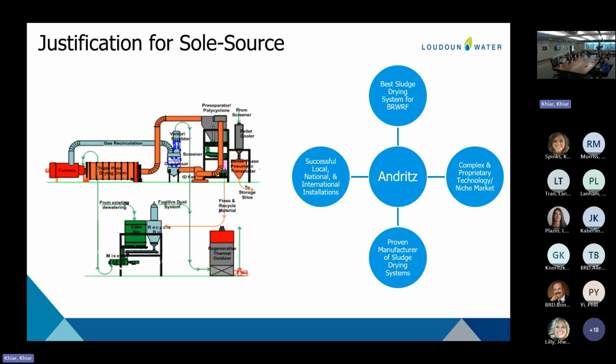It's a triple pass drum, and inside the drum is rotating. Inside the drum, the recycled pellets act as the core or the nuclei for the forming pellets. There's a process of lifting and moving as the drum rotates. The pellets make their passes through the drum and form. Basically that cake sludge forms in layers on those nuclei, or the word is accretion. It kind of accretes to those nuclei.